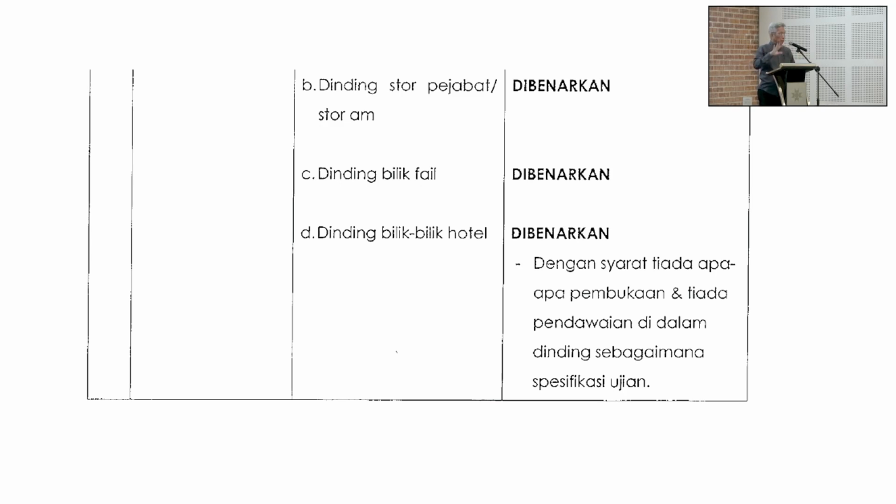So Bomba is saying it's perfectly okay to put the separating wall in the hotel rooms. It's not of real concern to Bomba. Now you can break off the room, it becomes a 2-room key, triple the room size, as long as it's still within the overall compartment limits of other residential building. No concern to them. So go ahead and use drywall. Fire rated, of course, but you can use drywall.